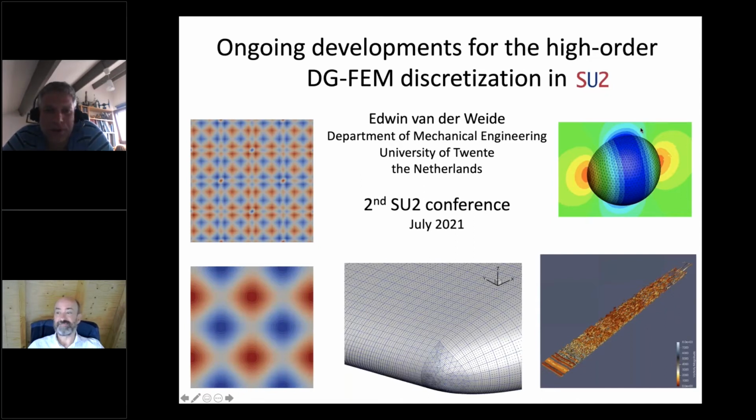Well, that's not only an issue of a DG discretization, but of any high order discretization: when you have a discontinuity, you have to go locally first order. We have done work on that, but more in Juan's group, on shock capturing, and that was done by filtering. If you do have a detector of the shock, the typical approach I would recommend is hp refinement: you use h refinement in the region of the shock and p refinement in the region where you do not have the discontinuity. And the question whether we can handle a grid that is too coarse to resolve a feature, we have not worked on that yet.